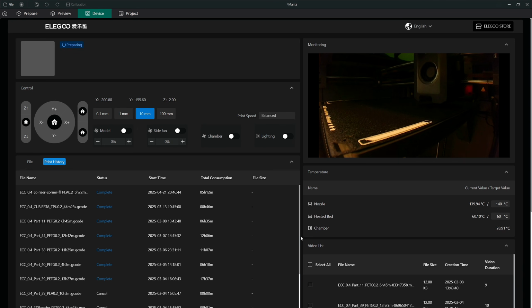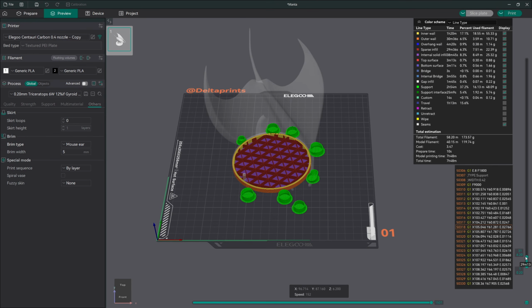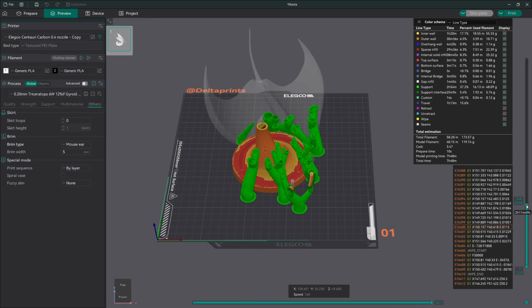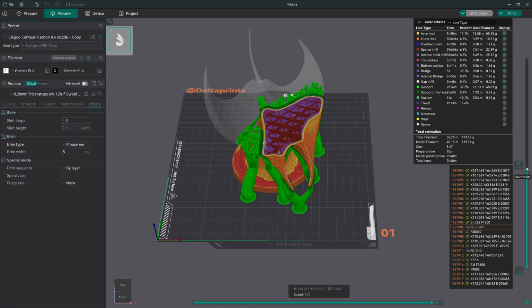Now that I've shown you the slicing feature in OrcaSlicer, I would like to go more in depth with it. Let's talk about what OrcaSlicer is actually doing when it's slicing your model. Just as you slice bread into pieces, OrcaSlicer cuts your model into thin horizontal layers. These layers guide your 3D printer on how to build your object layer by layer.